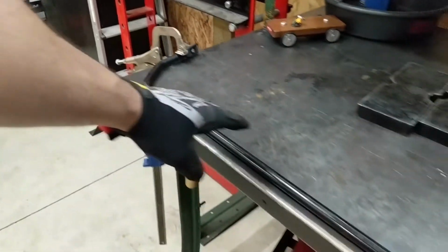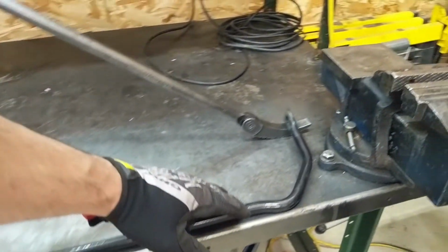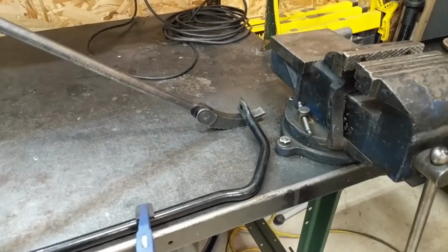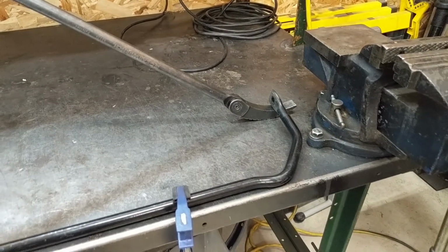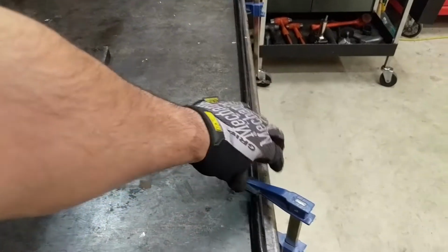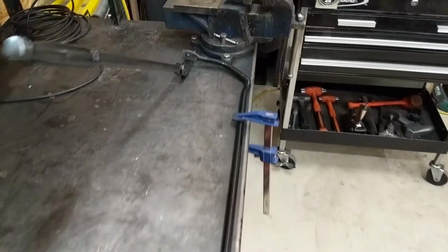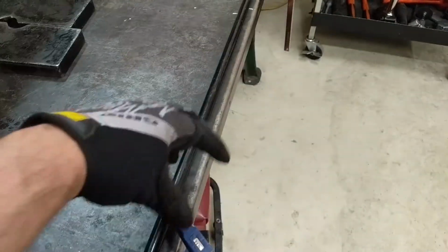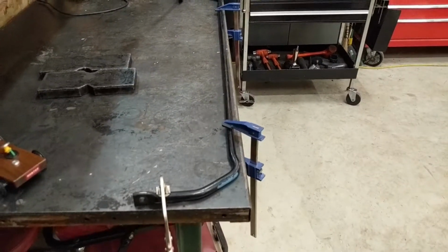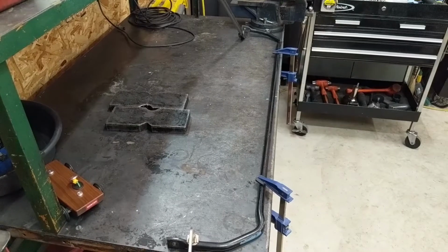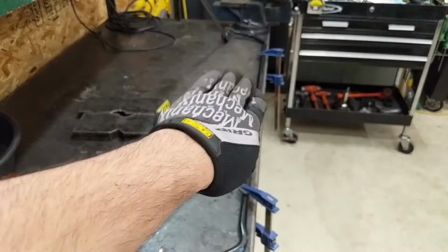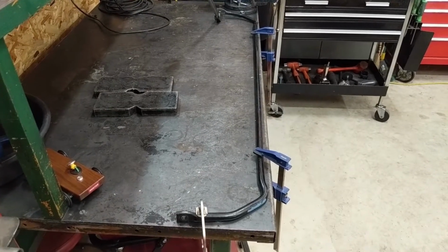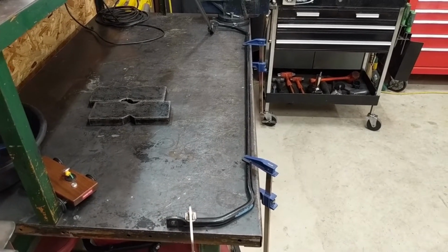That energy transfers through the spring steel to the opposite end, to the other side of the suspension, to help control the stability of the suspension as it tries to move. The mount bushings are going to mount the bar to the chassis or to the axle on either side. And through the movement of the suspension, as forces are acting on one side of the suspension or another, this bar is going to be able to twist. And that twisting motion is the characteristic of the spring steel, and it's going to transfer that energy to the opposite side.